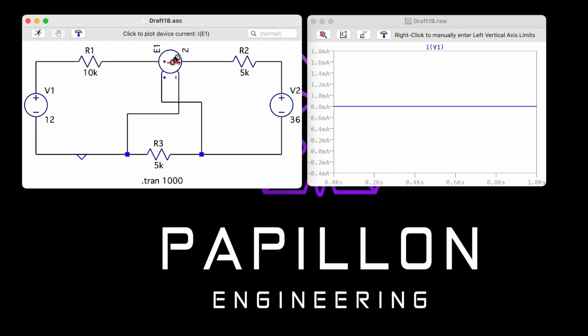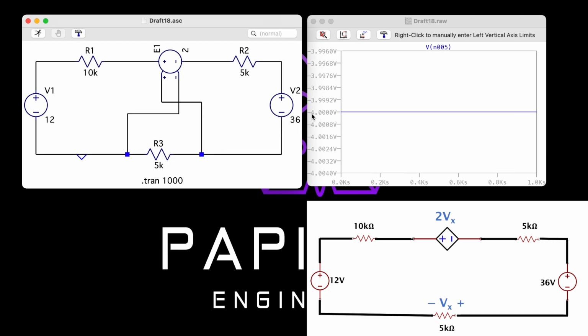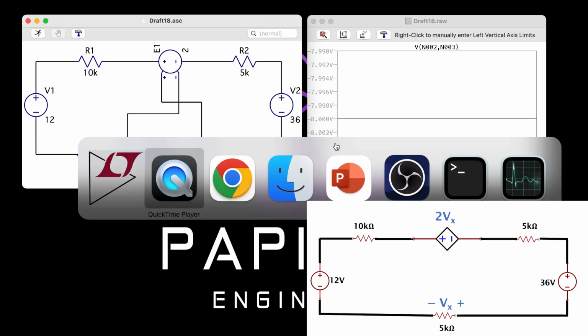As you go through it, more importantly, now we have to also look at the voltage. What we're expecting for our voltage is a 2-to-1 ratio. On the bottom, the Vx, as you can see here, I'm getting 4 volts, so technically minus 4 volts with the simulation. Then if you look at the top node for our dependent source and I check the voltage there, probing it from one side to the other by holding down the left click button, I'm getting minus 8 volts, which is what we anticipate the solution to be, a 2-to-1 ratio of the dependent source.